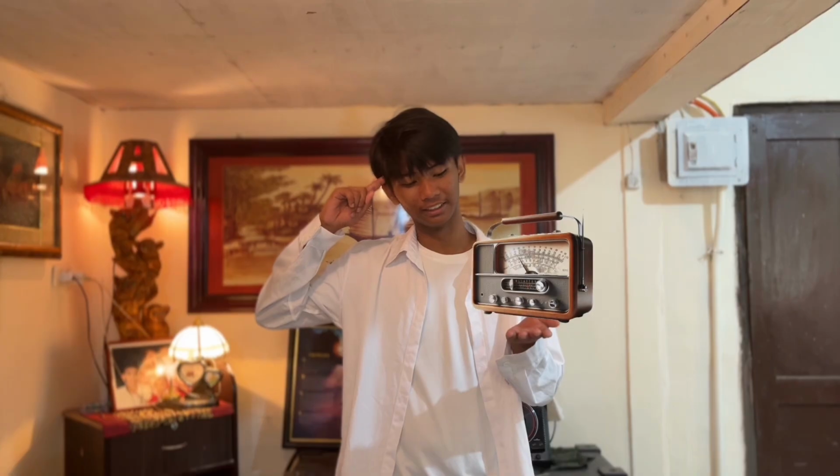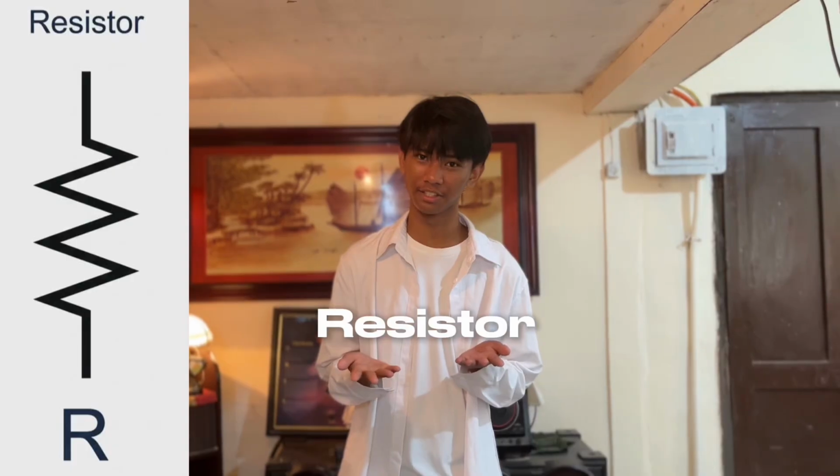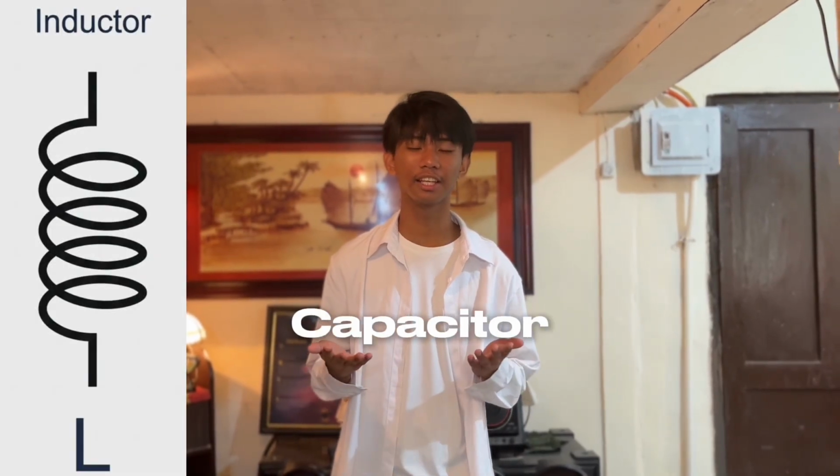And the control room, where all three elements combine into an LRC circuit. Impedance Z controls the current, and at the resonant frequency, XL cancels XC and the current peaks. That's how a radio finds its station. And that's LC oscillation powering every oscillator in the world.